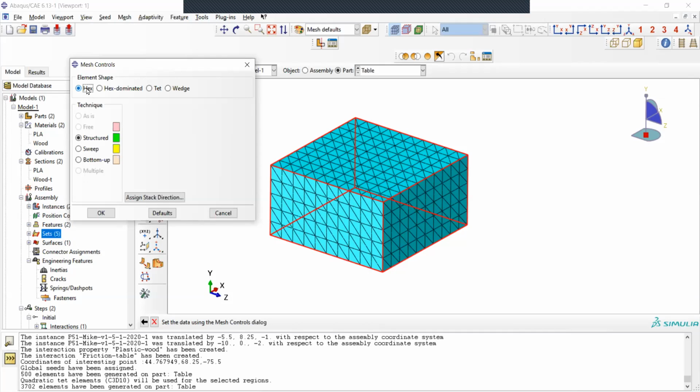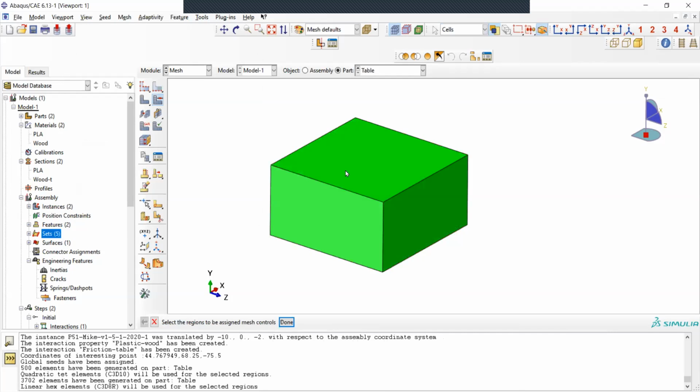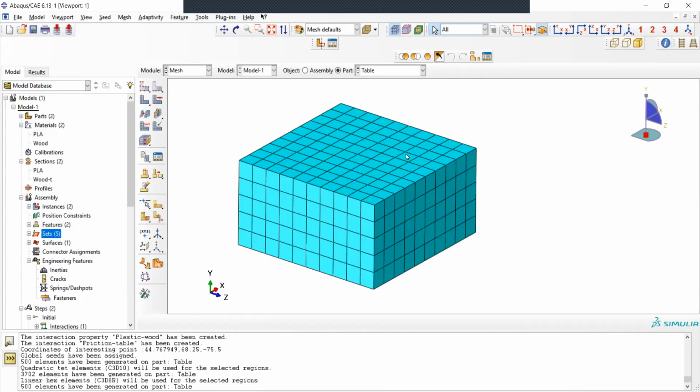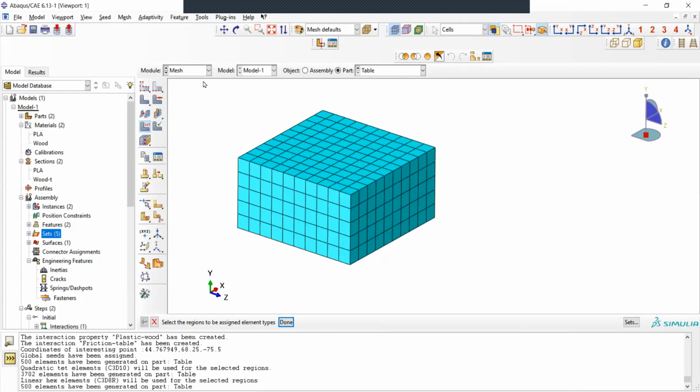It will give you much more accuracy in the simulation, and it will also reduce the number of elements. So if you can always mesh everything as a hex, that is the general preference. So this already is a very simple part, not much to say about it. But besides the type of elements, you have the mathematical definition of element, which is in the element type. I click on it, I can select the entire part, click done.